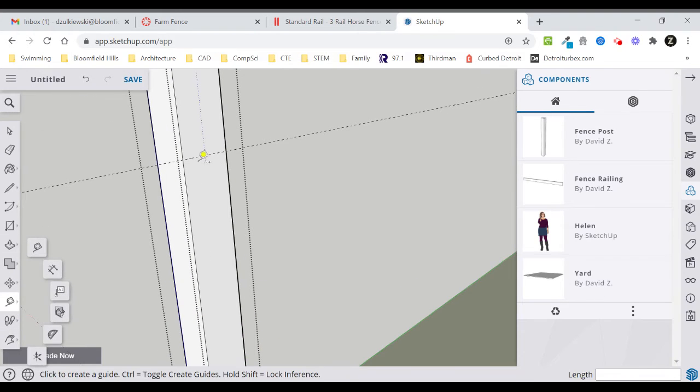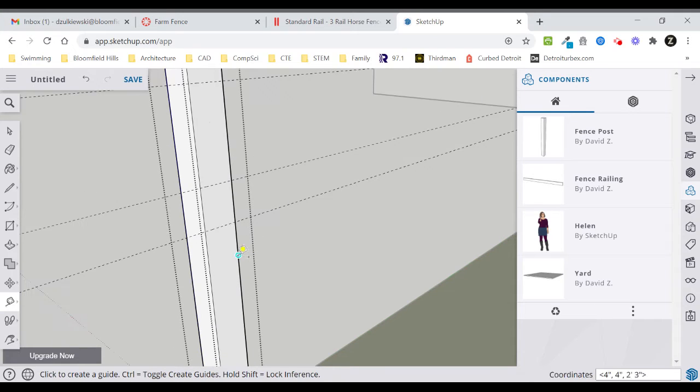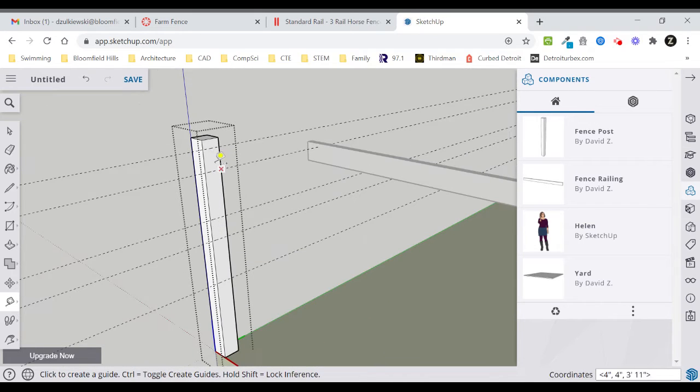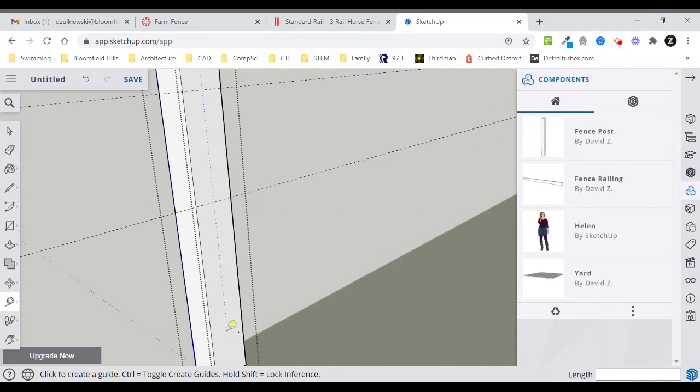And how big was that railing? Well, that railing's 5 inches tall. 5 inches. Again, check those dimensions in the lower right corner of my screen. Enter. All right. And then I'm going to go down another 10.75. Those are the spacing dimensions that have been given to us in our assignment. So I have 2 inches down and then 5 inches for the fence post, 10 3/4 of an inch down, and then 5 more inches for another railing, and then 10 3/4 down.